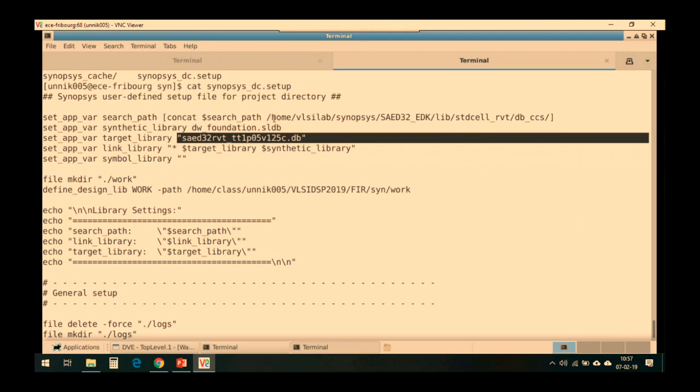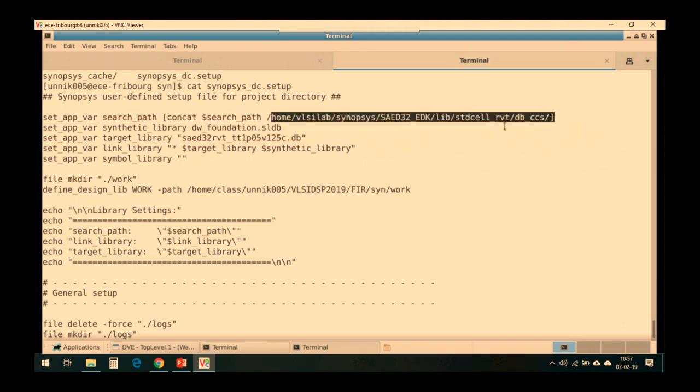In this library, if you read this part, there are multiple standard cells available which you can work with, in either the low VT range or high VT range, at different corners, either fast or slow. But for the purposes of this class, we've just shown you the typical corner, so you can focus more on the design aspects than on improvements based on the technology.